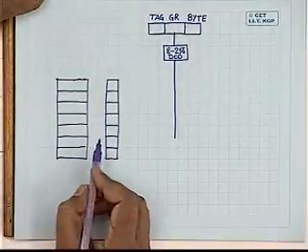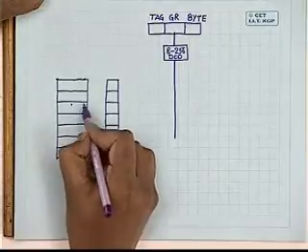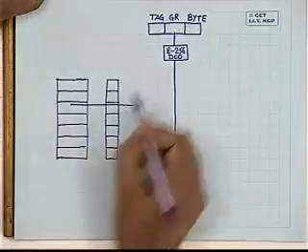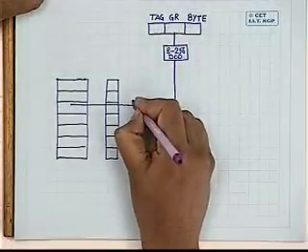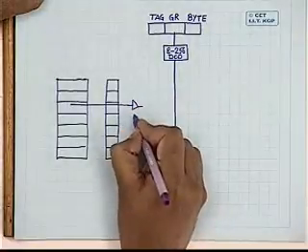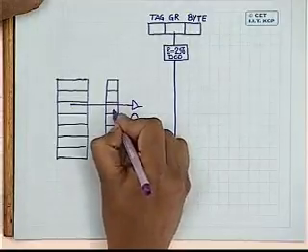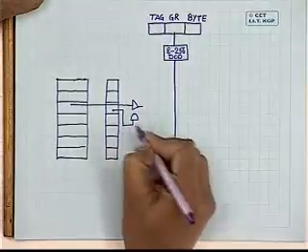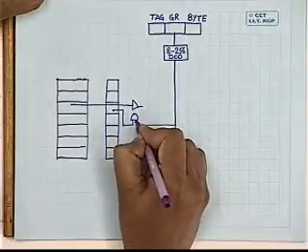So the logic will be something like this. I will compare the content of the tag memory location with the tag field that is present. So this will pass through a buffer, and to activate the buffer, what I will do is I will take the ANDing of the corresponding valid bit and the corresponding output of the decoder.